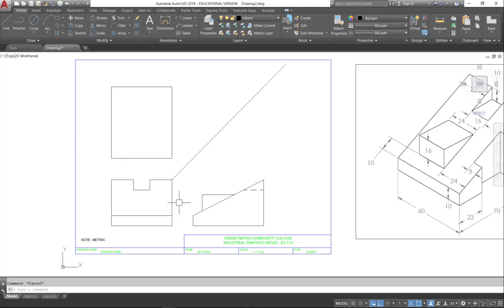And I'm going to project that back over into the front view. So I'm going to draw that line over. Draw the front line. Now as I look at this guy, it says that it's 24 inches over from the right, so let's offset that 24 inches. And then it's another 24 inches to the other side. So I'm going to fillet that. There it is. So there's that in the front view.